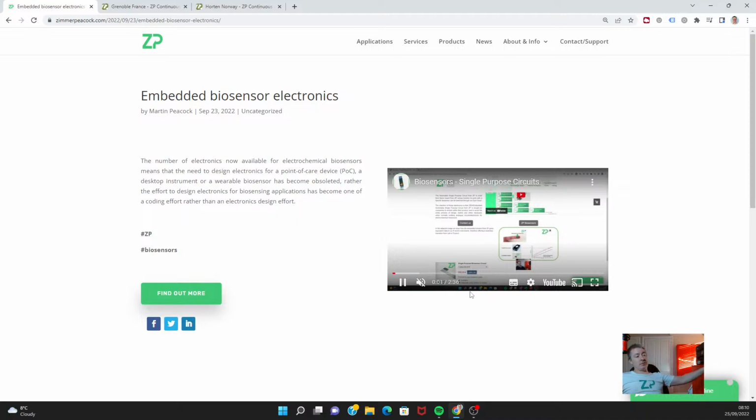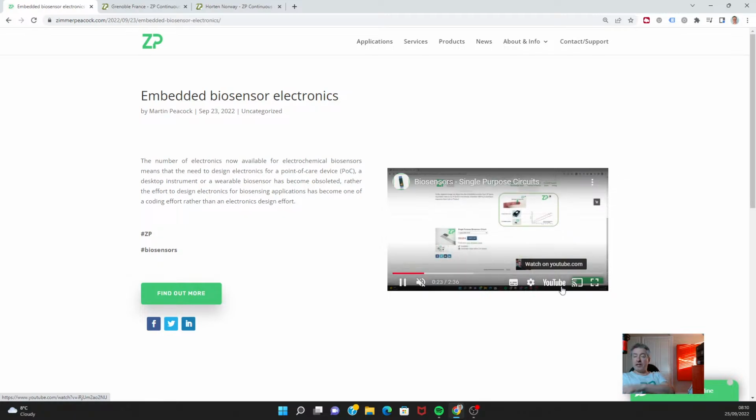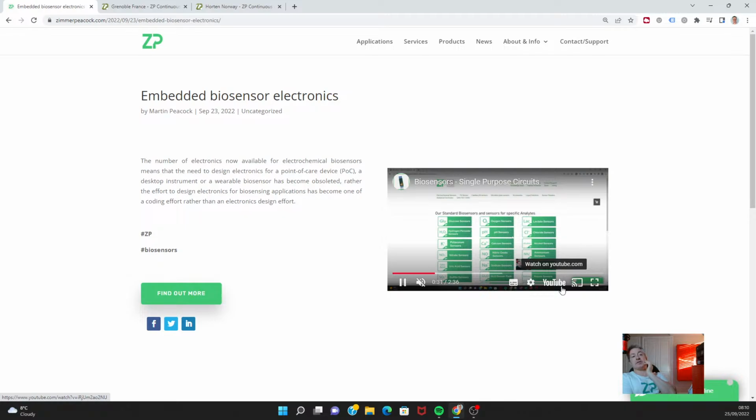So over the years, sensors and electronics around biosensing have got smaller and smaller. I think electrochemistry in particular really opens the opportunity for shrinking sensors. I've said this before, but it is easier to generate a voltage and measure a current, for example. Sometimes generating light, even with LEDs, is fairly energy intensive. And then those photons that you generate, for example, from an LED, may have to interact with some chemicals, and it's that interaction that could be the source of your signal.